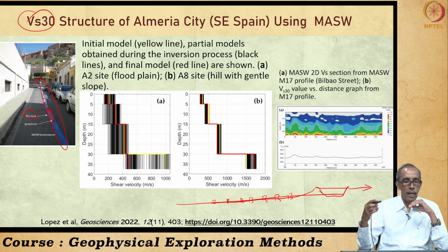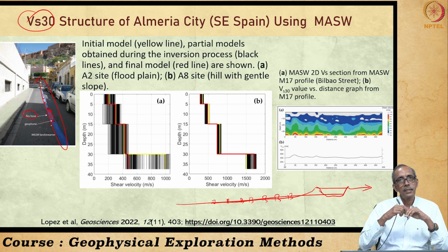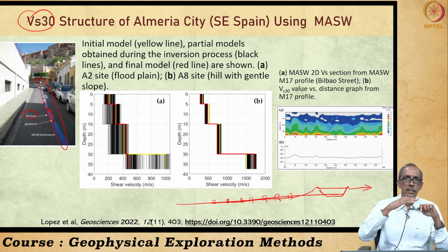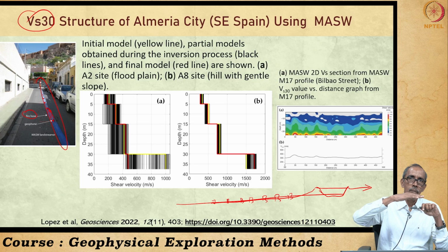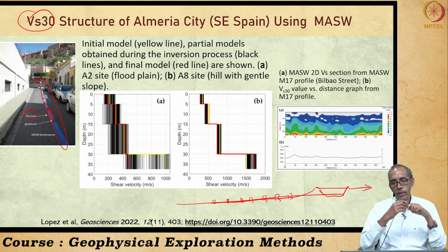right. And to this hose pipe we attach the geophones, right. That means geophones are not having any spikes, it is not going to have a firm contact with the earth. So, some signals will be lost, but to compensate for that we may add some weights around the geophone, so that the geophone part of the hose pipe is firmly resting on the ground surface, right.